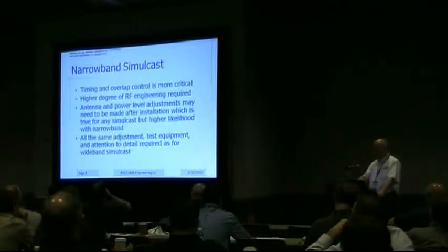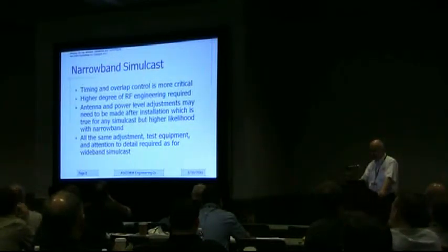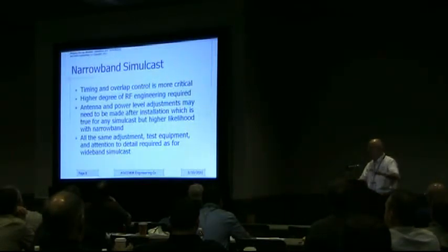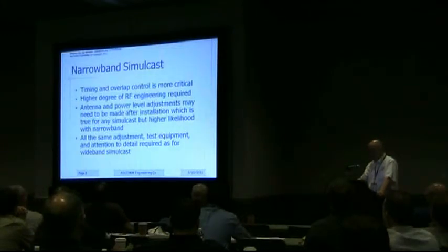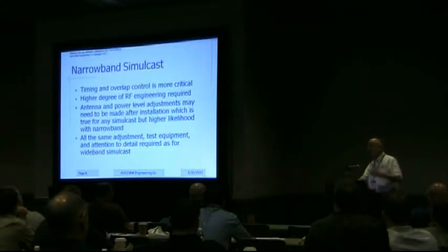Okay, so for narrowband simulcast, the result here is that the timing and overlap control is more critical. A higher degree of RF engineering is required. That's not like your master's or PhD, but more detailed RF engineering is required, because you're going to find that trying to manage the overlaps is difficult. We've talked about this for years: people have a non-simulcast system, they've got all high sites, and because they want to convert to simulcast, they just want to convert all their high sites to simulcast. It doesn't work very well that way.